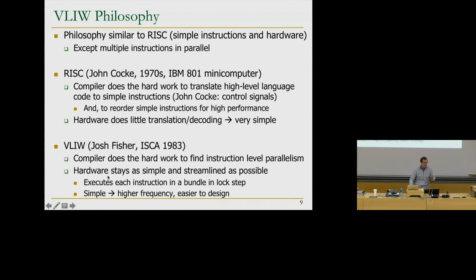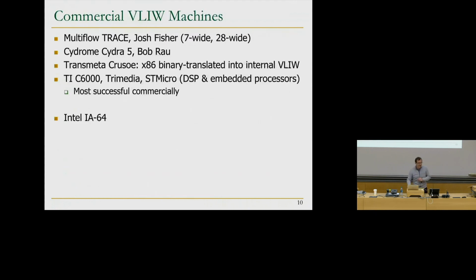And this still keeps the hardware simple. As a result, you can have a higher frequency and probably easier to design hardware, but the burden is now pushed to the compiler. As a result, there's been a lot of work on compilers. I'll give you some history over here. So commercially, VLIW has been successful in some domains, but not so successful in the general purpose domains. We'll see what the reason was.